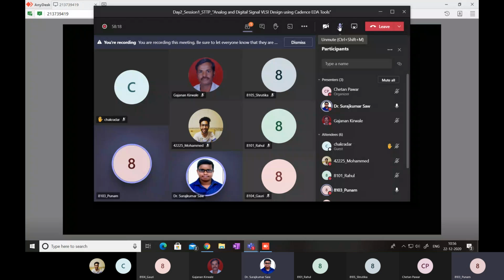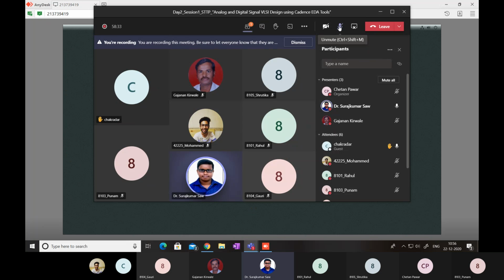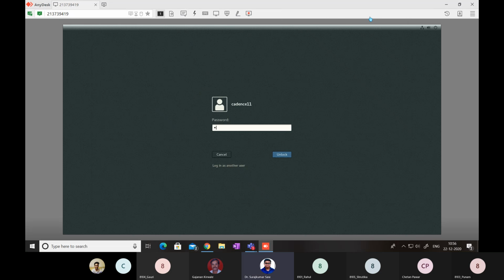Very good. But in the PMOS, you have to connect VDD, right? So what you need to do is these two PMOS will be connected together, and that will be connected to VDD here. As I type VDD, select place VDD here, right? Now it is good. Now you can see this terminal, this terminal, this terminal, and this terminal are open.